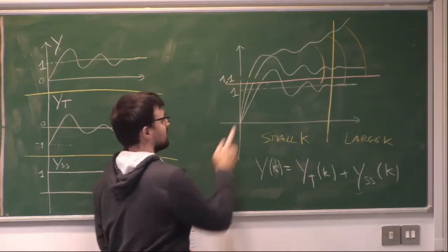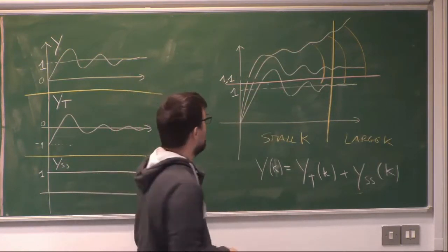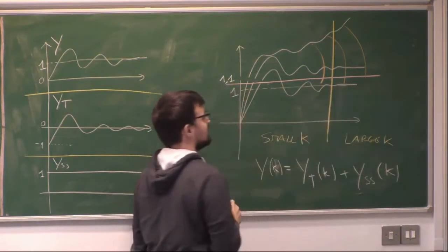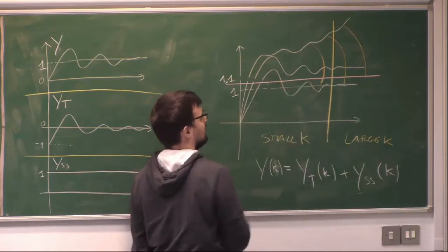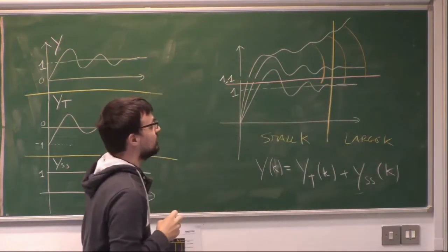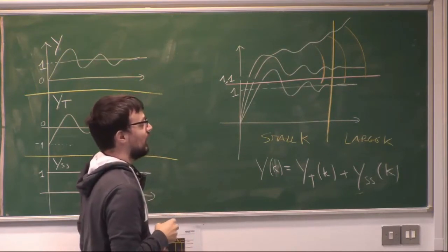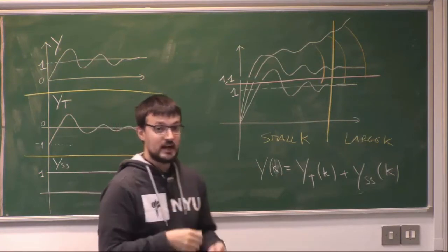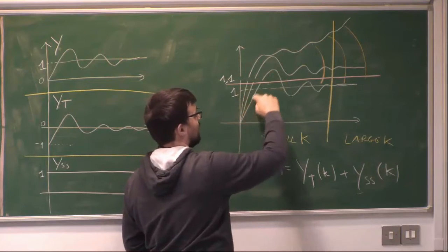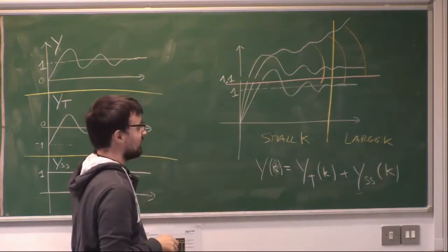And if we cross this line, then the device will break. We see that in this case, even though we have good steady-state accuracy, we are crossing this line when we are in the transient behavior. So our transient is not good enough for our system. Okay, we have to design a new control system that assures us that our response will always be below 1.1.